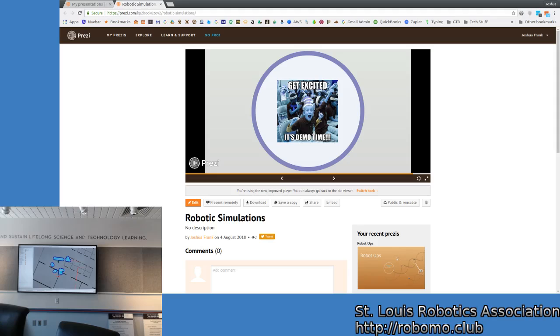There's the global cost map, and this is used more for long-term planning. It's very similar to the local cost map, but it doesn't update as often, and the robot uses it for navigating from room to room.